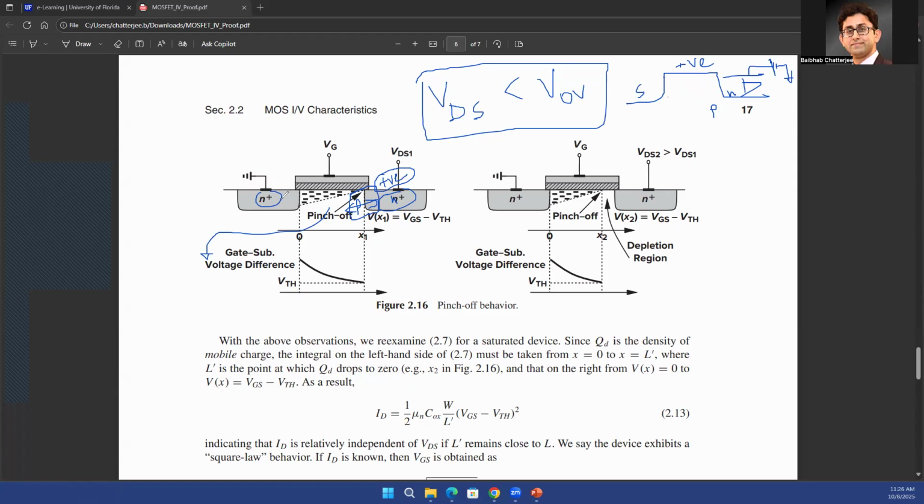So there are multiple process technologies. You may have heard about, let's say, Intel 16 nanometer, Intel 7 nanometer, TSMC's 3 nanometer, 1.6, like 16 angstrom, and so on. These different process technologies will have different properties. And they might say from the foundry that, oh, now we have doped the source region even more. So you can get more amount of current from the same device. So it's a choice of the device designer. The circuit designer has to work with whatever the device designer provides.